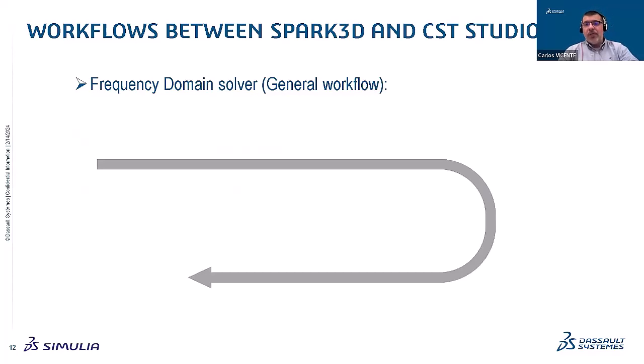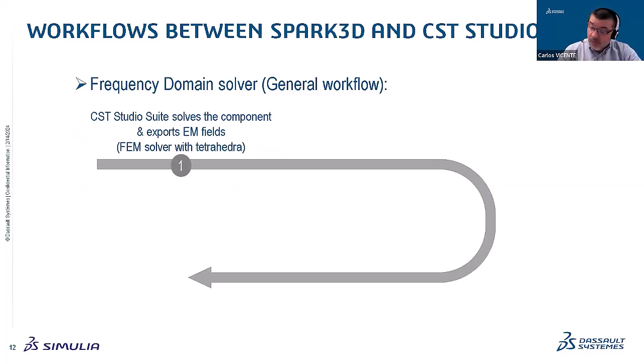Okay, so for the frequency domain solver, the workflow is relatively simple. First, of course, you have to solve the structure in CST. Basically the link we have between SPARK and CST Studio Suite is through the high frequency finite element solver with tetrahedra, okay? And then of course there you have to define the field monitors you want to use in SPARK3D. Mandatorily, you need to have an E and H field monitor per frequency you want to use in SPARK.